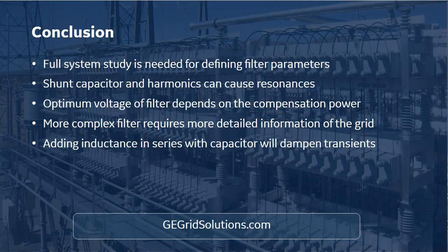So I would say that from somewhere around 1 to 2 megawatts, that's the smallest power we can typically do in the 33 kilovolt range for these renewables, from my perspective at least. So anything smaller than that is not really that practical. There is no practical upper limit, so anything can be done.